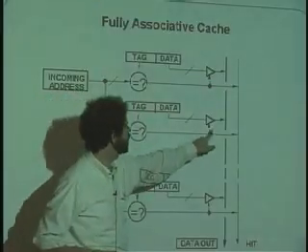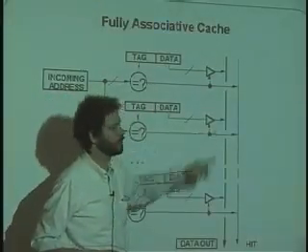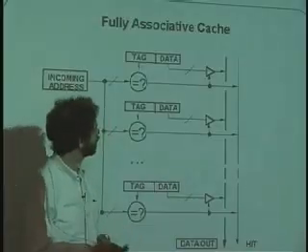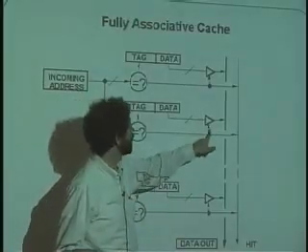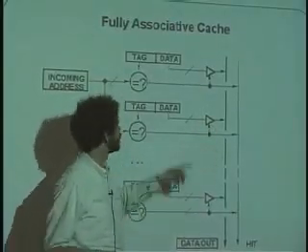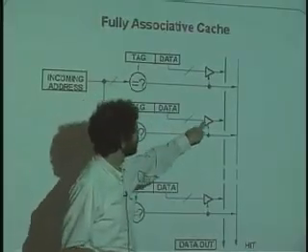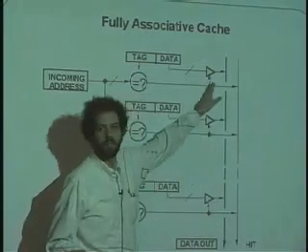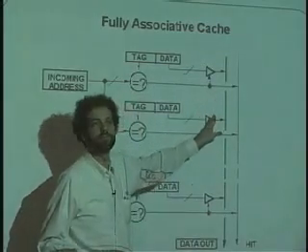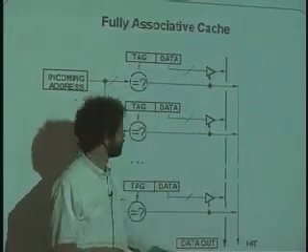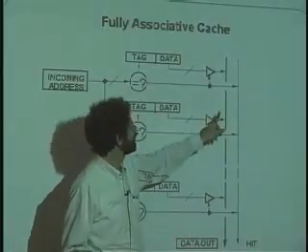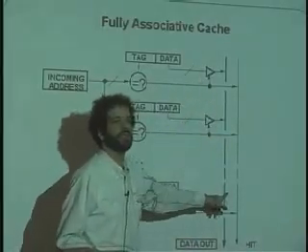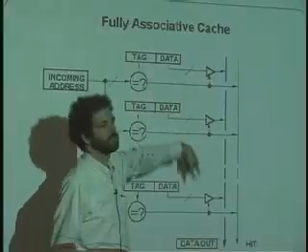And so we enable, this is actually a type of gate that you guys haven't seen here, but it looks like a buffer, but it has a wire that goes into it on the side that says go ahead and allow the data here to pass out to over here. You can think of it just like a switch. You can think of all of these triangles here as a giant selector for choosing which of the inputs here gets to go out.